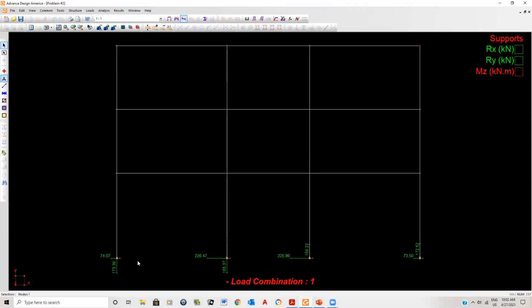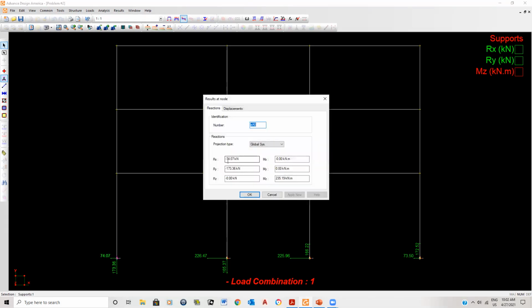And if you're doing this on the exam, just double click on it, so you'll get the same. Here you'll notice it says minus 74.04, but then it shows 74.04 because it means it's going from right to left. And you have a negative, that means it's going from up to down. So you can see even the program does it correctly. Once you put the right direction, you do not put the negative sign. The negative sign is to mathematically show you how you should interpret in which direction the force is acting.